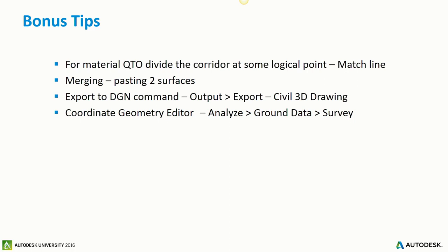Does that make sense? To control that, what you end up doing is you actually extract a polyline, a border. Let's say you're going to paste one surface onto another. You get the border from this surface, and you trim the surface where you're going to paste this guy at that specific point. Now, you are better controlling that surface. You're not letting the software triangulate to whatever point beyond that. You are controlling a point, maybe you can offset 1 foot or 2 feet, whatever that is, but you've got a 3D polyline, which is extracted as a border from one surface that gets pasted as the inside boundary on the other surface, and then you paste the surface. Now, you control what gets pasted.